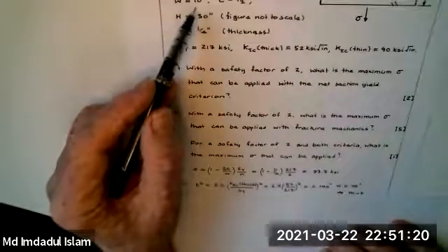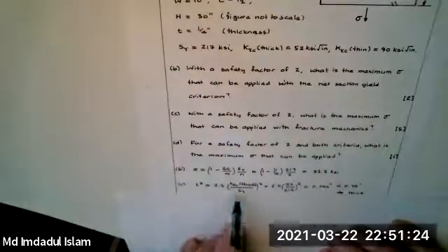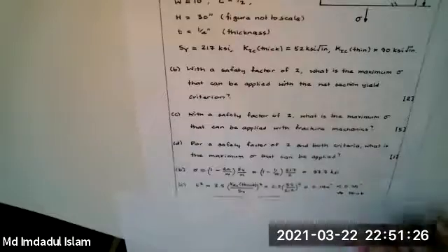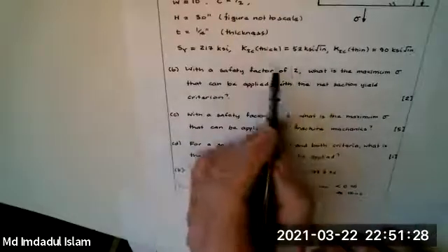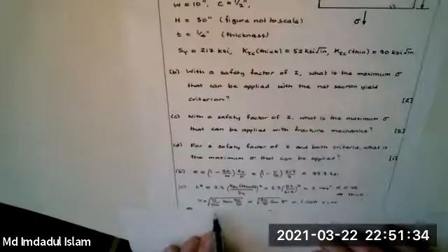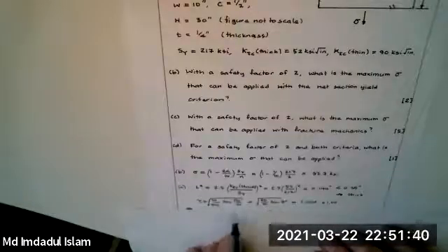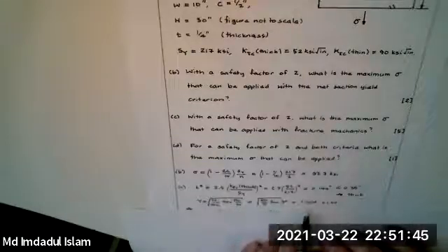You might think a quarter of an inch compared to 10 inches is a factor of 40. That's not what you're comparing with. You're comparing with material properties when you make this. So this is a thick plate. So you have to use this K1C thick. Then you might decide, well, what about edge effects? Well, in this case, T is a half, W is 10, so this is pi upon 20. Okay, if you divide 180 by 20, you get 9 degrees, and you get 1.04 to 1.00.